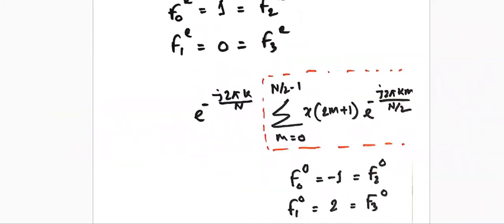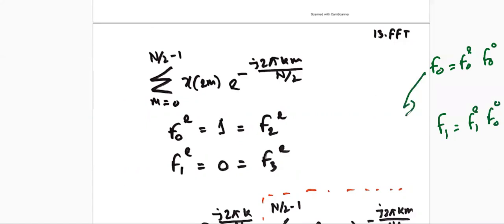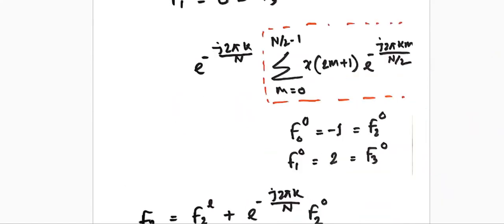So again, whenever you have found f0 and f1, with f0 even and f0 odd, f1 even and f1 odd, that means you can also find f2 and f3 completely. You do not need to do any sort of processing, because you already know those values, and that actually saves the time and the multiplication, and that is the clue.